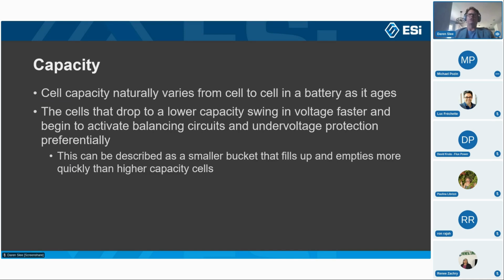So the voltage will start to potentially trigger protection circuits, instead of charging ending naturally or discharging ending naturally by design, by the charger controlling that, or the capacity measurement of the amount of current that's leaving the pack, where the pack says I'm fully discharged, like your phone says 0%.